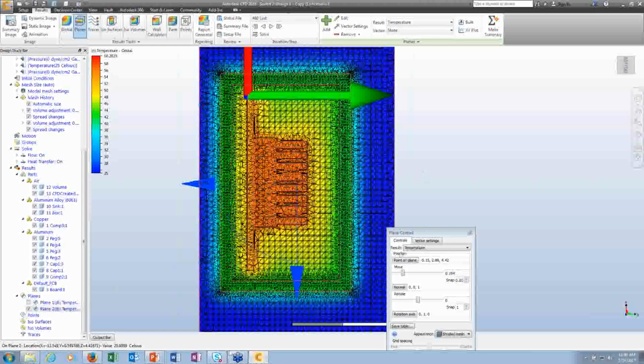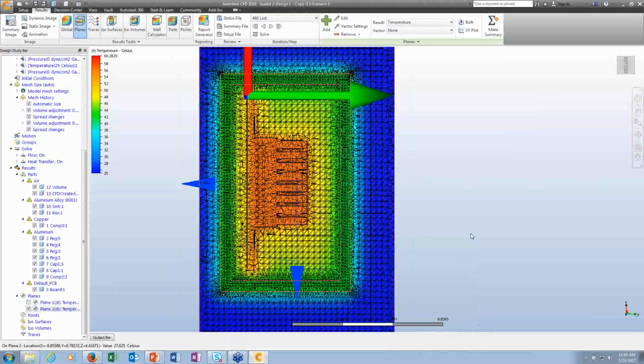One other thing you can do here is turn on gap refinement. It's basically going to help so you don't transition from too coarse to too fine of a mesh. It spreads the seed points at a more conservative length and ends up putting more mesh in there. Chances are you're going to get a better mesh in between those fins when using gap refinement.